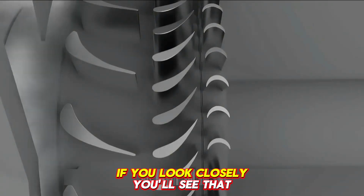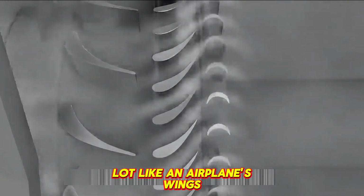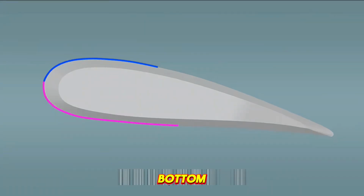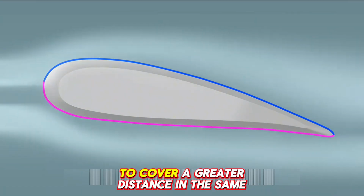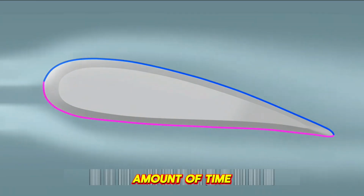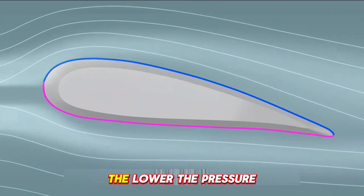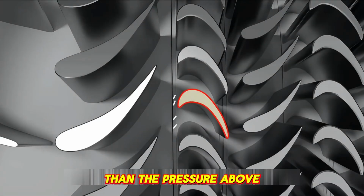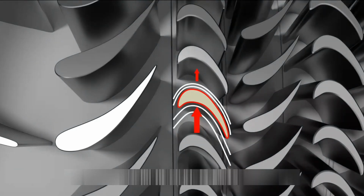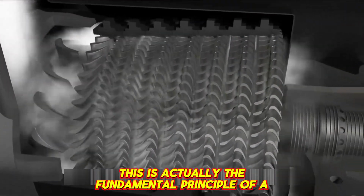If you look closely, you'll see that the blades of the steam turbine are a lot like an airplane's wings. The top is a bit longer than the bottom, so the steam has a longer distance to travel along the top. To cover a greater distance in the same amount of time, the steam on top must flow faster. The faster the flow, the lower the pressure. This causes the pressure below to be greater than the pressure above, creating an upward lift, which pushes the blade and makes it rotate. This is actually the fundamental principle of a steam turbine.